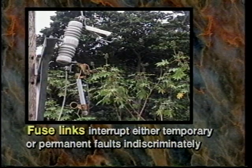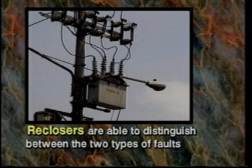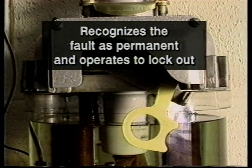Unlike fuse links, which interrupt either temporary or permanent faults indiscriminately, reclosers are able to distinguish between the two types of faults. They give temporary faults repeated chances to clear or to be cleared by a subordinate protective device. If the fault is not cleared, the recloser recognizes the fault as permanent and operates to lockout.